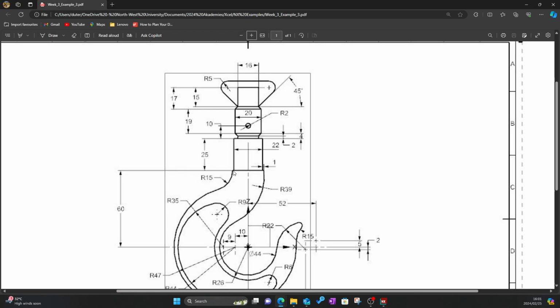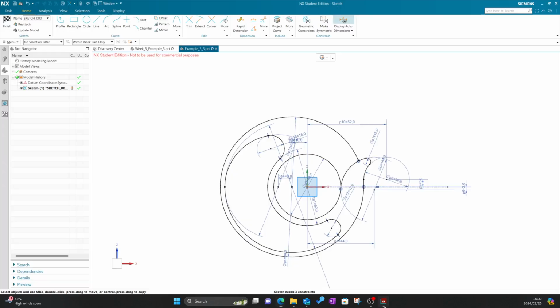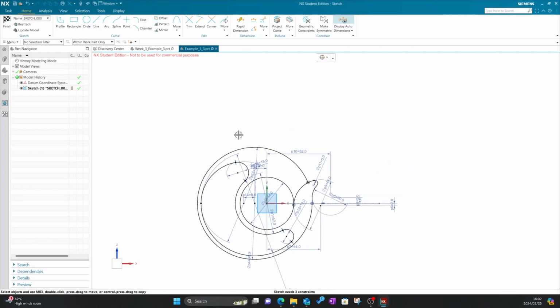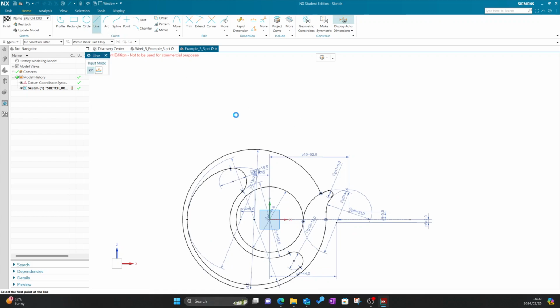So first we'll need to create that horizontal line. So that will give us the limit, if I can name it like that, from or to where this curve will stretch. So this curve will stretch somewhere from this circle where it's a tangent constraint to this horizontal line, and you'll see that this horizontal line is 60 millimeters from the top, and it has a width of 22 plus 1 on each side, so it's 24. So we can quickly create a line. You can just quickly draw a line. We know it's 24, and then click.